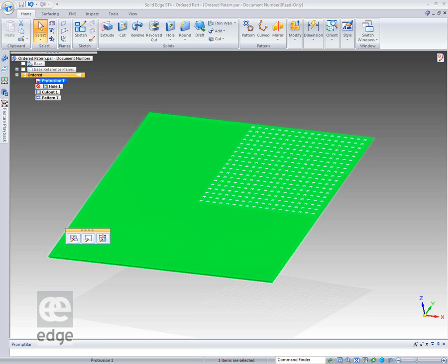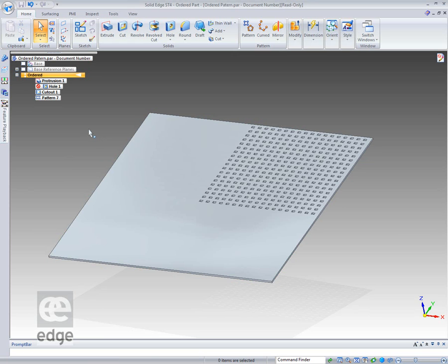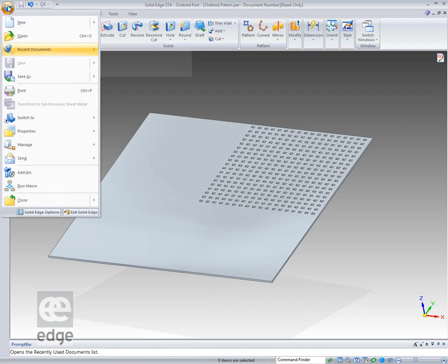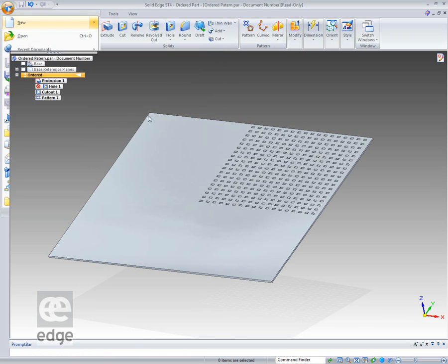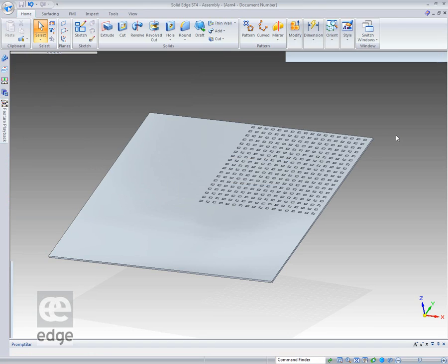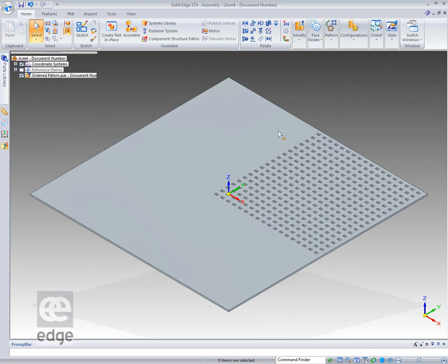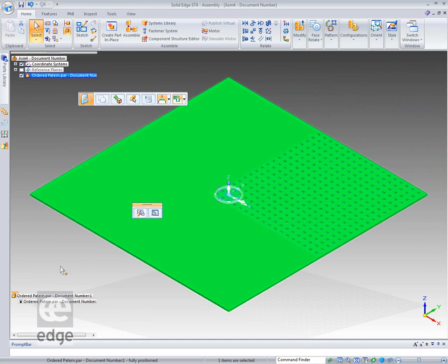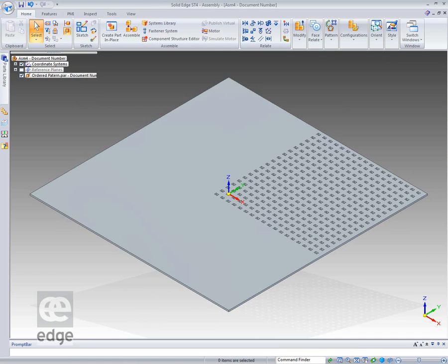Wayne, how did you delete the grounding on the part? Oh, sorry, that's assembly. No, that was straightforward. You select the part. Let me see if I can do that. If I just make an assembly out of this, so I've dropped this part into an assembly. If I select that part, you'll see down here on its assembly characteristics, it's grounded. All I have to do is select that and hit the delete key. It's now not grounded anymore. So I hope that answered your question, Wayne.